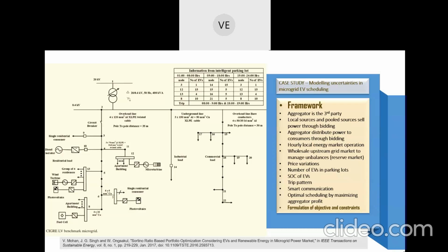We have already discussed load flow. Now into this load flow, we are incorporating an optimization problem also, based on the preferred objective of the operator. So it becomes an optimal power flow problem. Basically, before the real-time horizon itself, the operator runs the optimal power flow problem and he gets the dispatch set points, and this is the schedule of the microgrid.